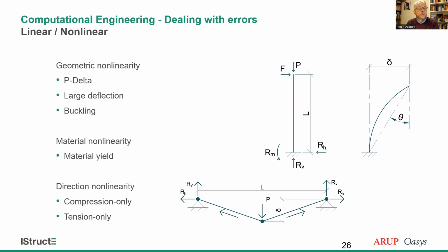Doubling the load or 1.5 times the load will not necessarily give you 1.5 times the moment or the force. You have to analyze these problems with the factored combined loads to give you the right results. They are non-linear, which means there's not a linear relationship between the loading and the results.